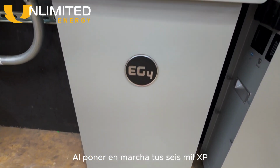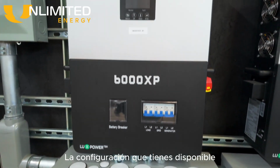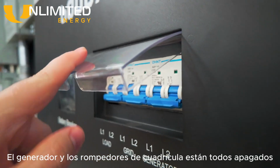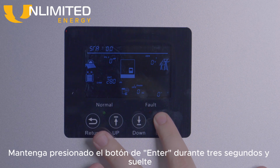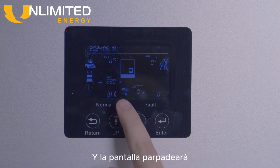When commissioning your 6000 XP, it's important to familiarize yourself with the settings you have available. Before we begin, ensure that your load, generator, and grid breakers are all in the off state and the battery breaker is on. Now to enter the settings menu, hold the enter button for 3 seconds and release. You should hear a double beep when you let go and the screen will be flashing.